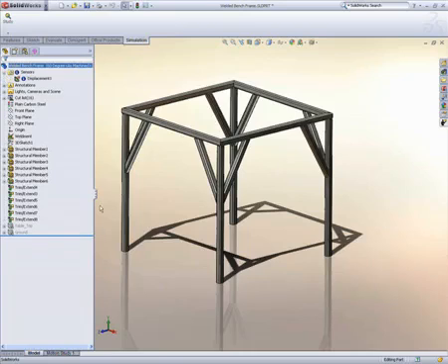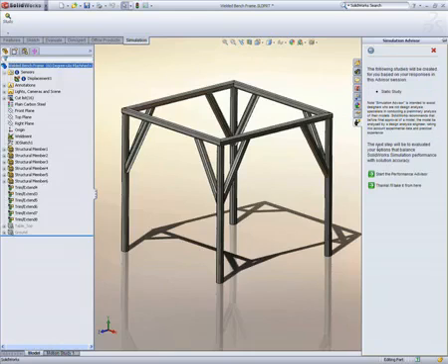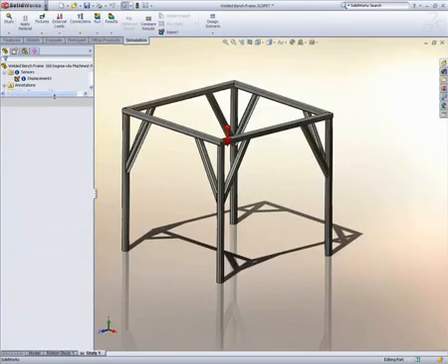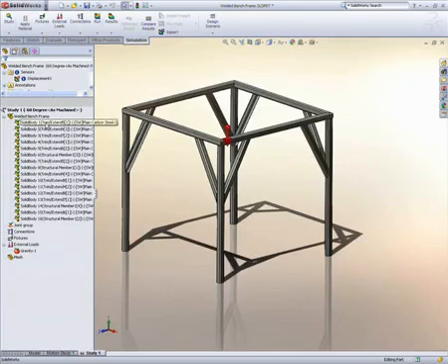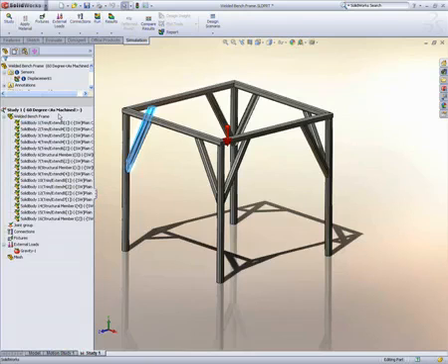There are several ways we can represent our design, and by default SolidWorks Simulation provides the most efficient way. Our structure is made of weldments, which are long and slender. It will represent these as beams, automatically using the section properties of the geometry in the simulation. You're free to adjust the representation back to solids, but beams allow us to get insight into which design is better in a matter of seconds. This is a valuable tool in the fast-paced design world where you need to quickly weed out designs that are not suitable.